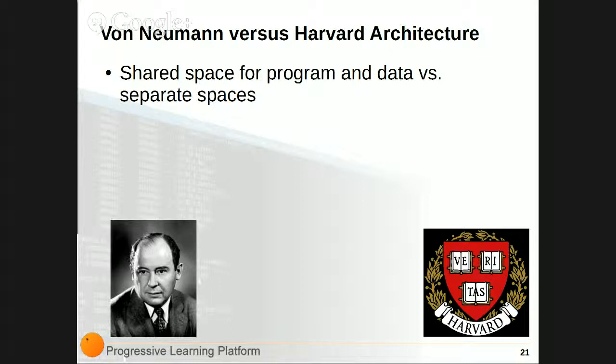If you can assume that both are operating at the same speed, it'll actually be slower, right? Because if you share program and data, when you execute a program, you need instructions every time, but sometimes you also need data when you are processing. So you need instructions being fed into your CPU all the time. Then you need data, but you only have one set of buses. Then you have the von Neumann bottleneck. Okay, I get my program. Wait, program comes in. Okay, data comes in. That's the drawback of having a shared program and data.